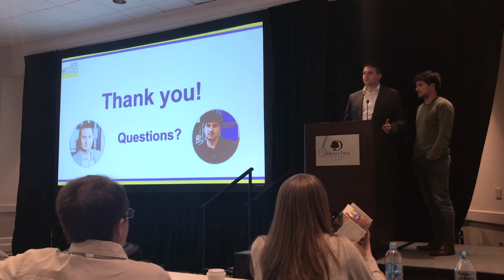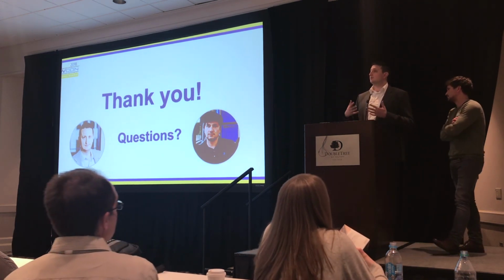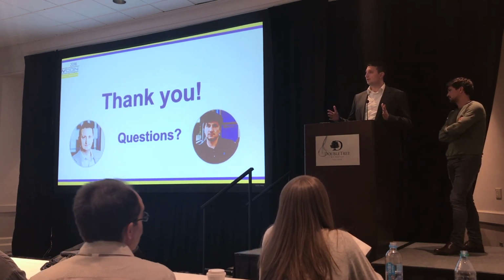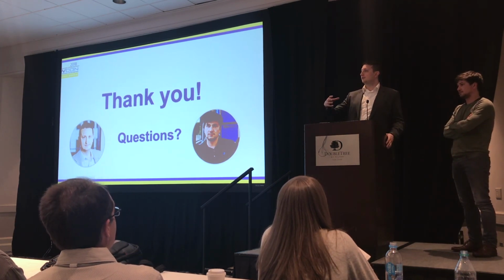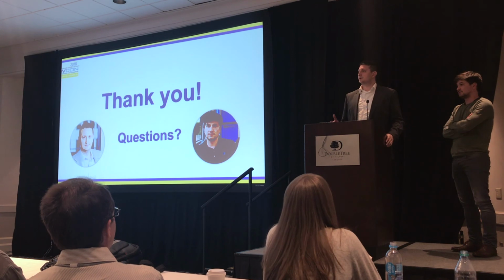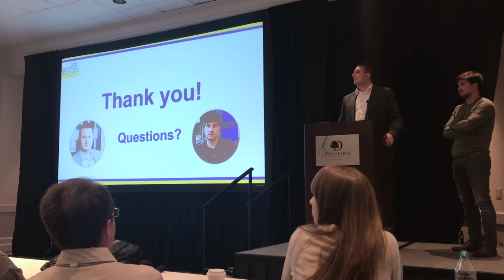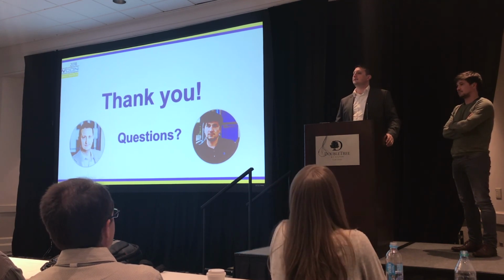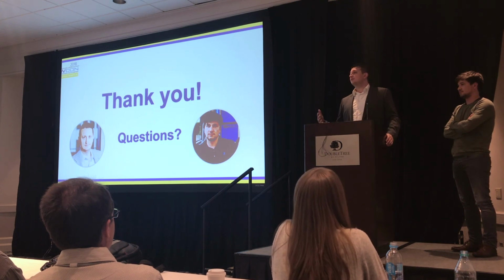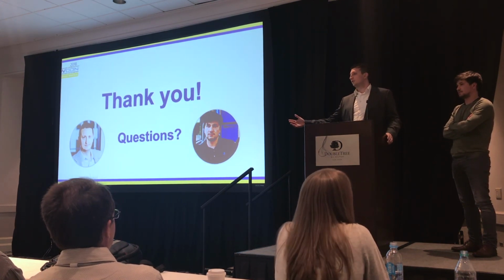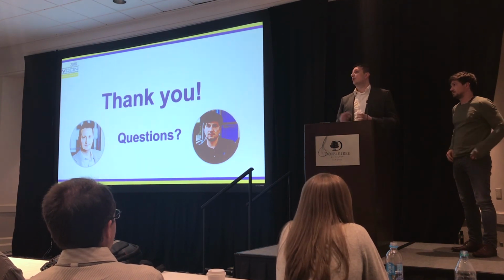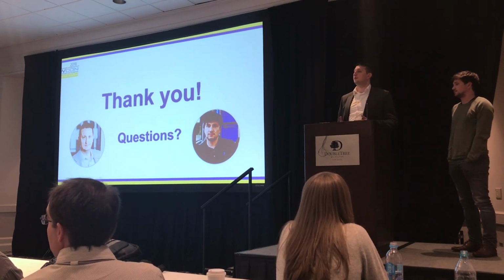Okay, so the tool being a formal tool, when it proves the assertion to be proven, it has its own depth, right? So it proves fully for the entire state space when the assertion proves. Does the user give it that depth? No. So it does this alone. Should you have bounded results, then you could discuss whether you need to increase the steps of the provers to maybe get a conclusive result, or if you're okay with the bound which is already there.